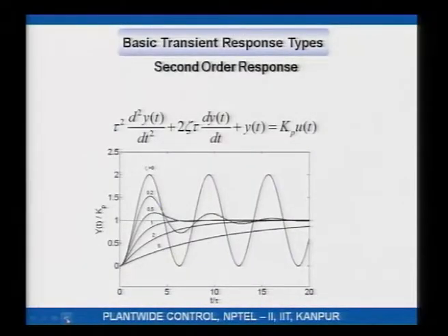In order to get oscillations, the system has to be underdamped second order at least. Okay. That is because maybe it is not appropriate to go into the theory of differential equations. So, let us just say, here is a second order differential equation, the simplest type, and this tau is again referred to as the time constant.